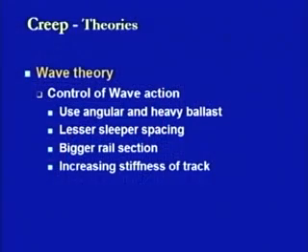Now, in this case, control of wave action is going to happen by certain things in the field, like we can use angular and heavy ballast. This is from the supporting condition, as we have discussed that we have to increase the track stability or we have to increase the track modulus. So, what we can do is use heavy ballast which is more angular in shape.